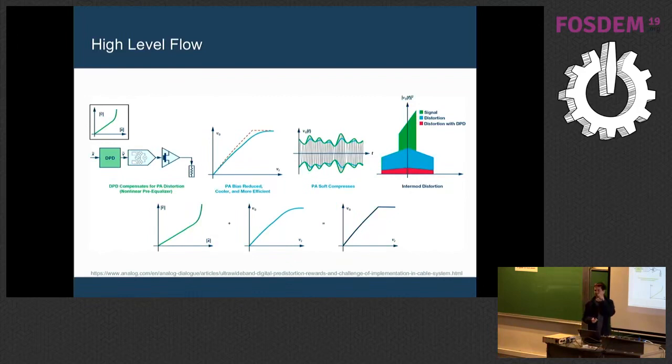First, it's going to be 0.9. You probably don't notice. But when it starts being really significant, that error accumulates, and all of a sudden you're getting this shape here. So what we want to do is, at the input, just increase the amount of power a little more than we think we need. So if we say we want 1 more dB, we put in 1.5 dB higher power. And in the end, hopefully all the math works out.